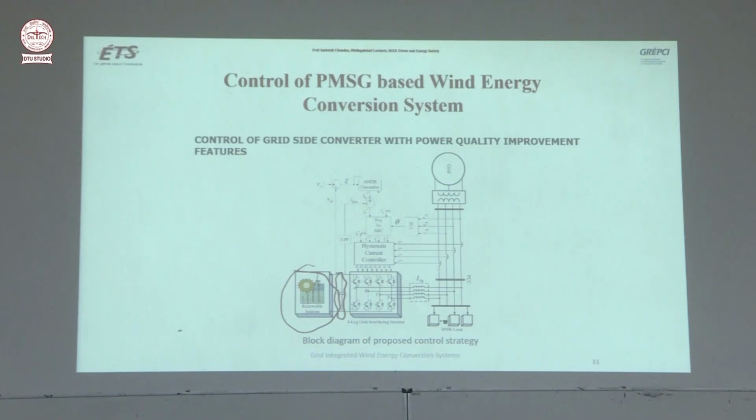Okay, and it is the same inverter. Basically, if you have a shunt active filter, and you want to integrate your PV or grid power, you connect at the DC link. The only thing is that you will have to increase the capacity of the IGBTs which you are using, because extra power is being transferred to the grid. So the size of the IGBTs will increase.